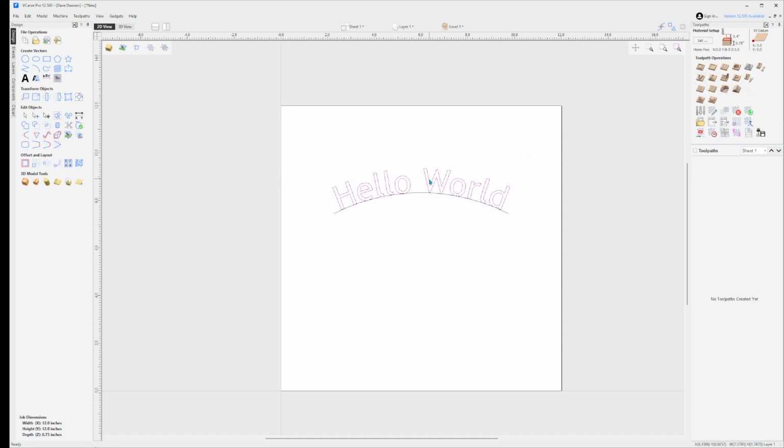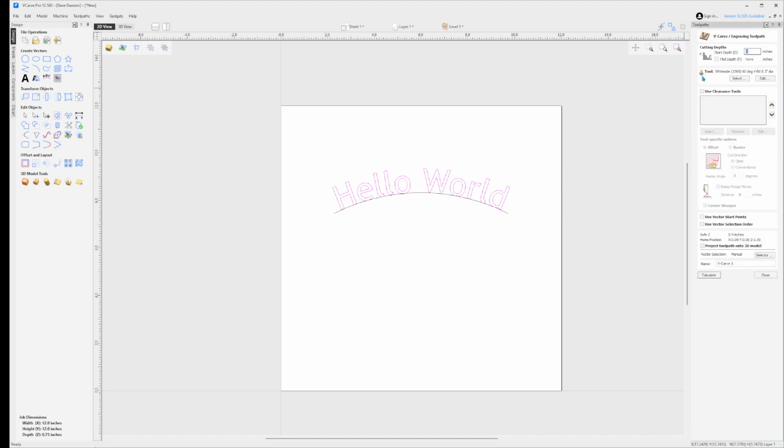And so we'll select the toolpath we want to carve. We don't really need to worry about that arc. That was more just for us to draw the line. We'll go ahead and pick the VCarve, and we're going to start it at 0. We're going to set a flat depth in this case because we don't want it to dive super deep into the wood. So we're going to set this at about 0.2 inches, or about 1/5 of an inch for those that prefer fractions. And we're going to select this.